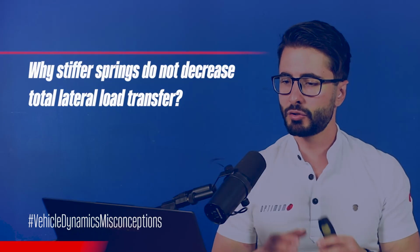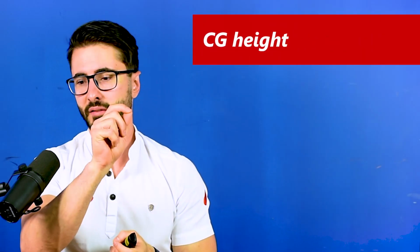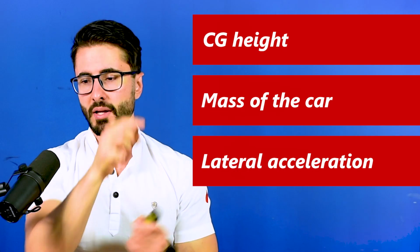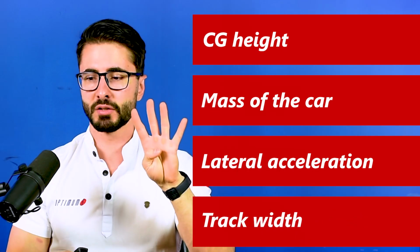Why do stiffer springs not decrease total lateral load transfer? A lot of people think that if you increase the stiffness of your vehicle and it's rolling less, it will transfer less load. This is really not the case. The total load transfer is only a function of the CG height, the mass of the car, the lateral acceleration, and also the track width. These are the four parameters defining the lateral load transfer.